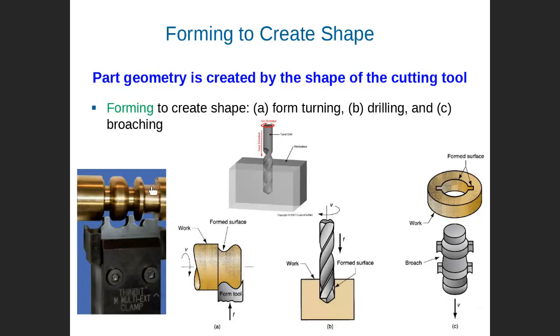If I would like to manufacture another shape, then this tool cannot be used anymore. You must create another tool. So this is not a general tool anymore, but a tool specifically designed for this shape. Then the tool approaches, not traveling. There is no traveling here, but the tool moves in the radial direction to form, not generate, the shape, as you can see here.